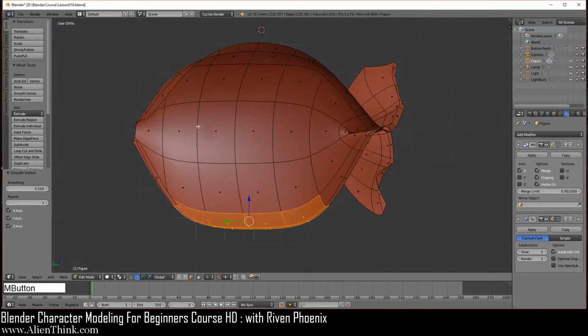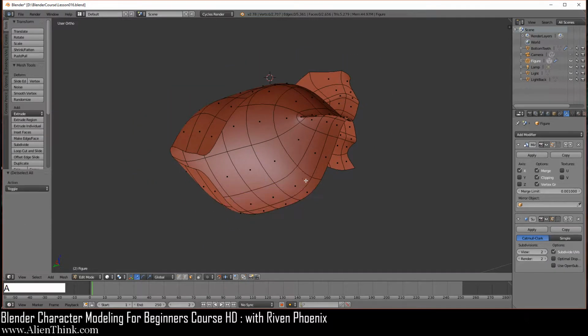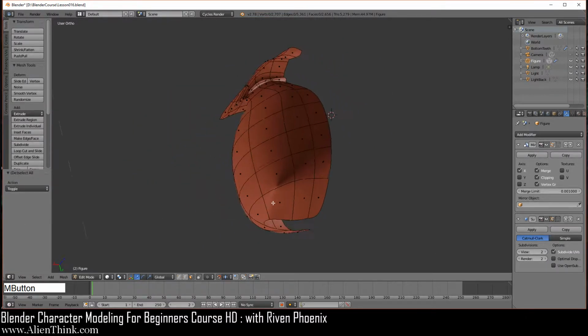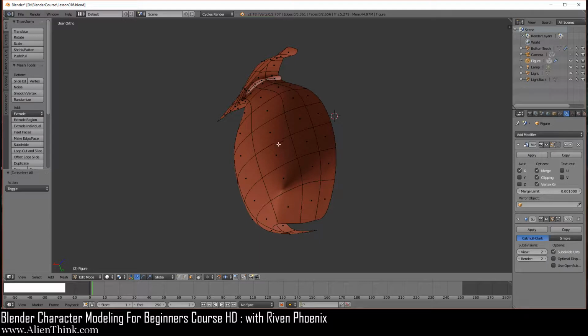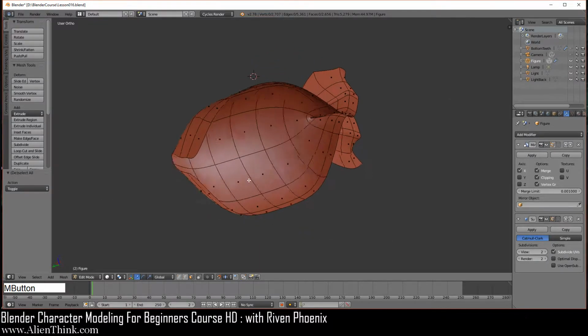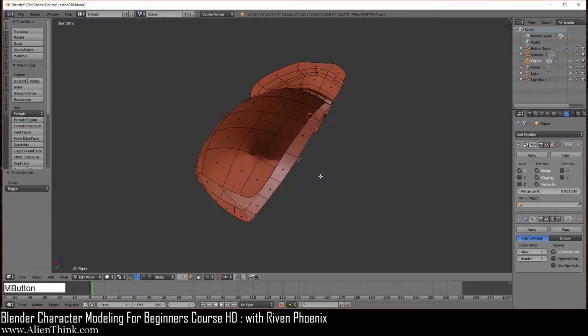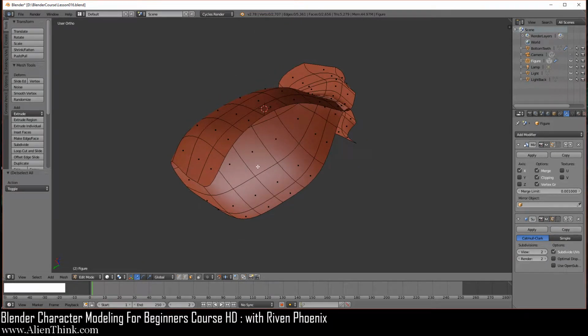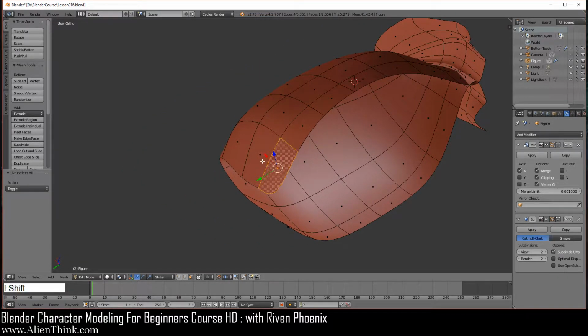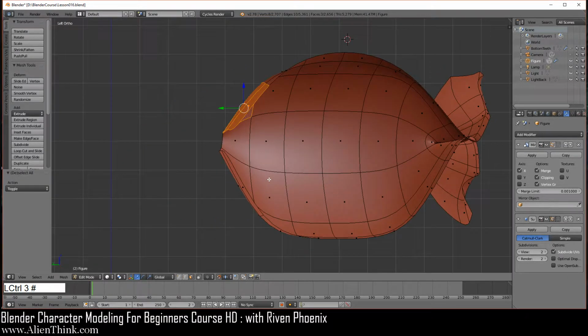So now if you look, now as I said, this is where it gets a little confusing, because we're seeing this idea here. These are the normals from the back. It's hard to see what's going on, right? This is really the inside. That's what you just need to get used to. We're used to looking at shaded areas. Anyways, click on this one, shift key down, this one, do Control 3.